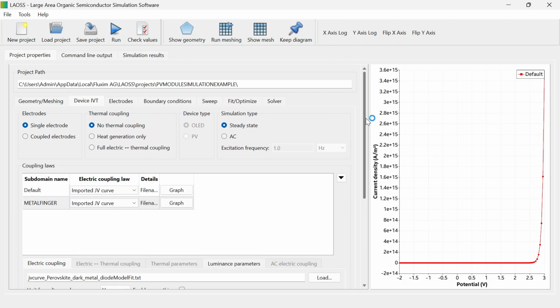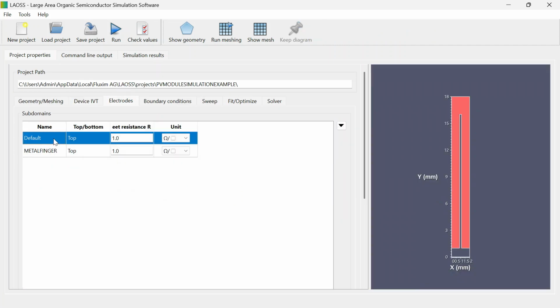So you can see now you need to move with the electrode tabs. In the default you can give here the sheet resistance value. That value we need to enter here is 20 ohm. You can see here the different parameters for the resistance are given. You can select any parameters according to your choice and your projects.